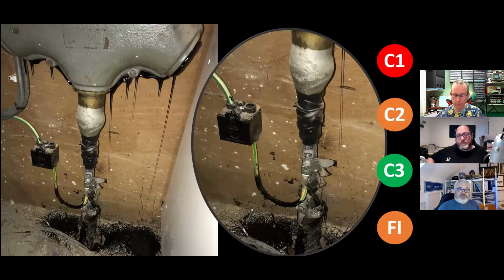And once that pitch all leaks out, you then have the risk of arcing or a short on the metal case. And if you report it to the DNO, fundamentally you've got an insulation medium that's escaping, haven't you? Yes, you no longer have insulation. It can be a loose connection in the head, actually. Yes, you're bang on. And I've just realised, Dave, that I'm missing a slide of a certain intake, which we could have used. We'll use it for the next one.